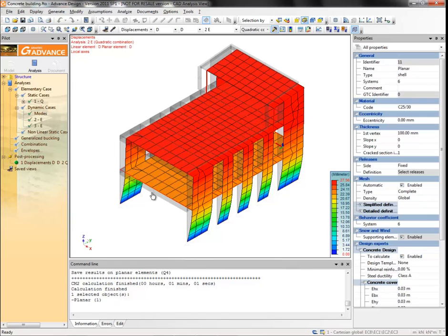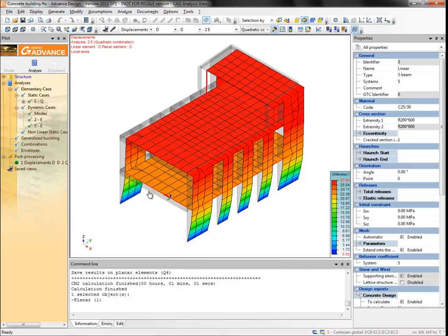Select a beam from the first level. Check the outline of the selected element to make sure the right element has been selected. If more than one element overlap at the point where you click, you can press the Tab key to switch between the different possible selections.